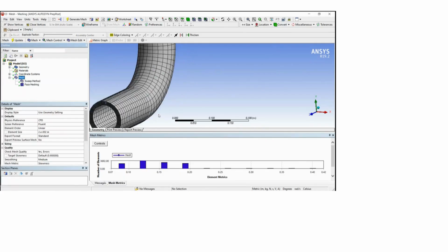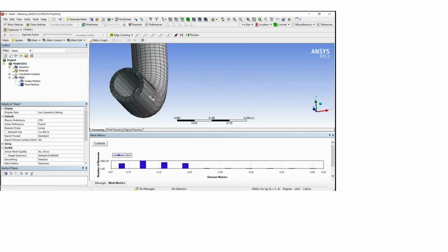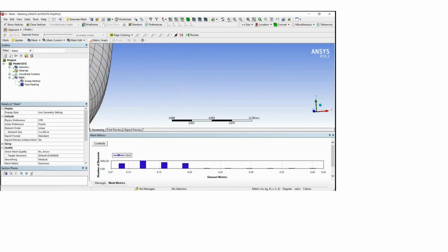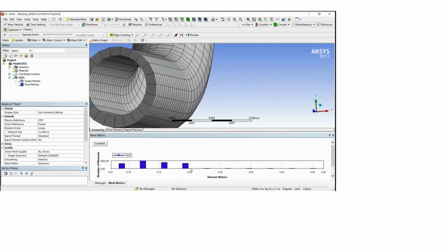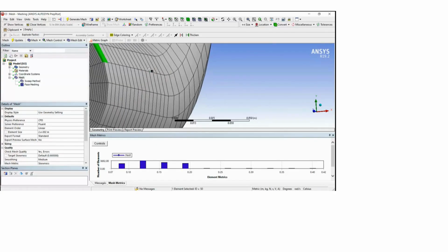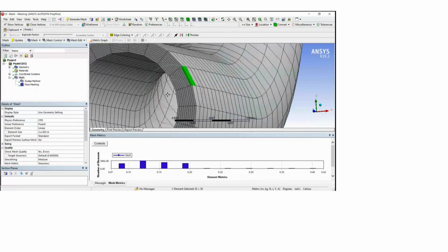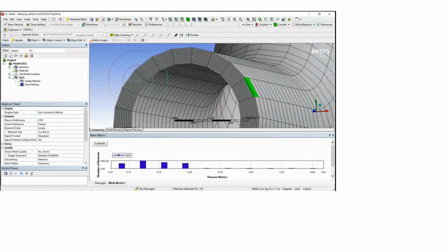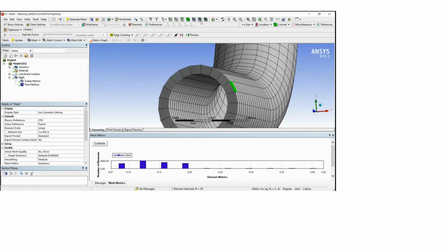So see, you can have a very good mesh in this region. It's also structured, and once we have done this, automatically the skewness has decreased from 0.65 to 0.4, which means we have approached in the right way. You can see this is also a very structured mesh, and overall we have distributed the structure. Earlier in some parts we were getting some waste cells, but right now it has completely turned into hex cells, which is a good sign. So everywhere we got a good structured mesh.